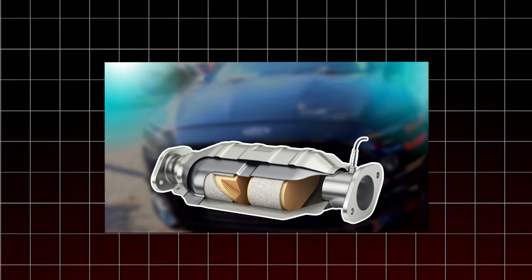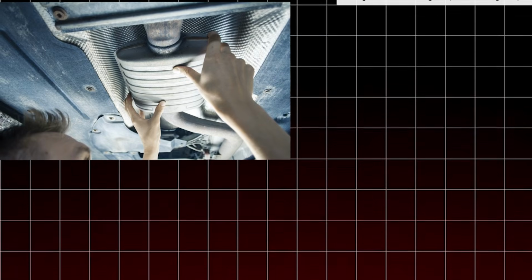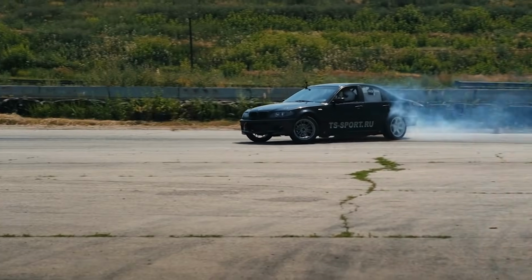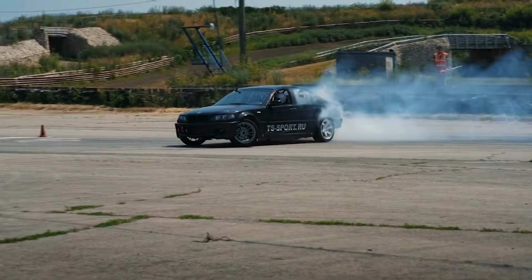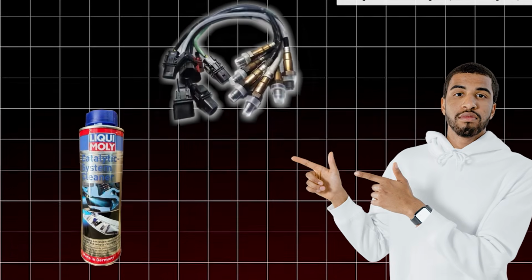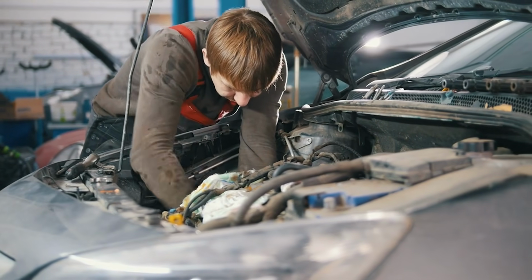In this video, we explain the P0420 code and how it relates to catalytic converter issues in older vehicles. Understanding this code is key to maintaining performance and staying emissions compliant. We covered solutions like using O2 spacers and catalytic cleaners and stressed the importance of correct installation and follow-up.